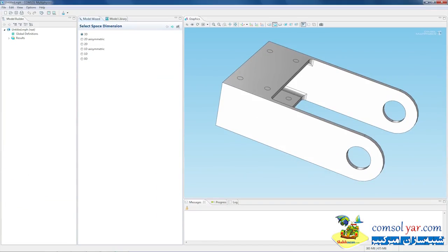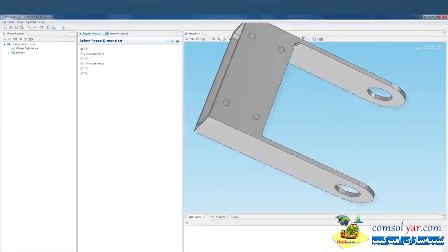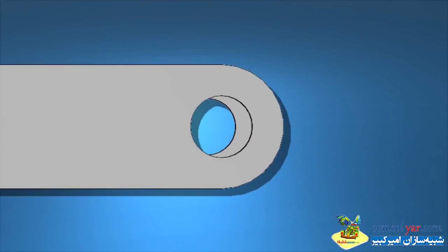This video will describe the simple process of creating a bracket model by setting up a static analysis and performing a parametric study for analyzing a varying load. After an initial analysis with the load applied to the bracket holes along the negative y-axis, the sweep will start at 0 degrees and rotate 45 degrees up to 180 degrees.